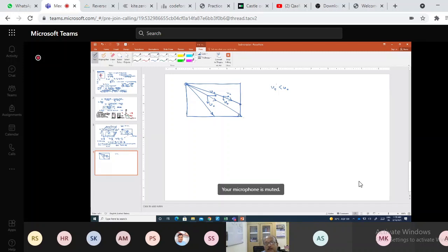In our definition, if it hits the bottom, it is retained. For this we have to consider that as the water gets into this section, the particles are uniformly distributed over the depth.